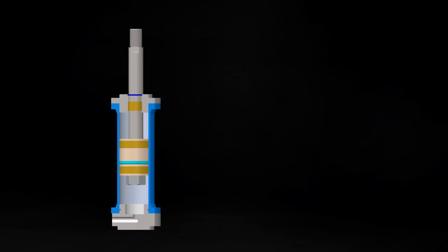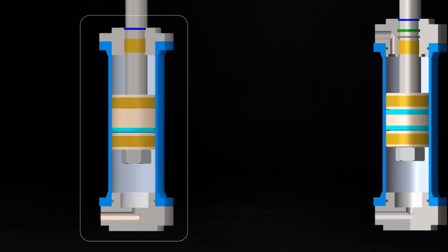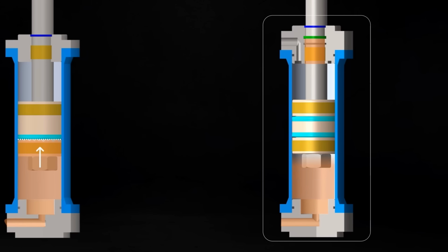Now, the key difference in designing a single acting and double acting hydraulic cylinder is that in a single acting cylinder, the piston has to seal the oil pressure only from one side, from the oil port side. But in a dual acting cylinder, the piston has to seal the oil from both sides, right? And not only at the piston, we also have to seal the oil pressure in the front head of the cylinder, between the piston rod and the front head. Otherwise, oil will leak through the head.